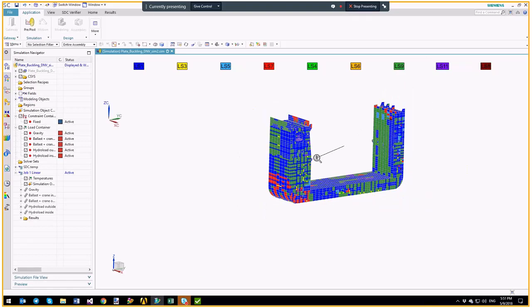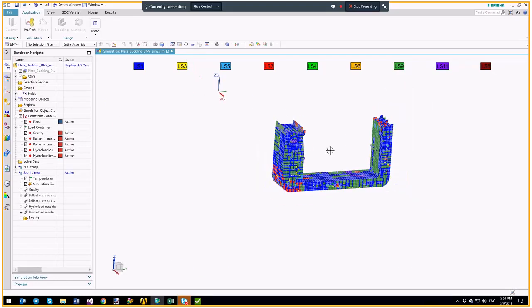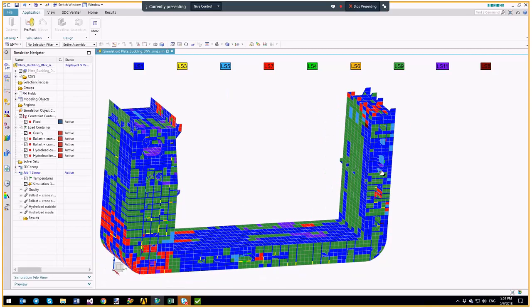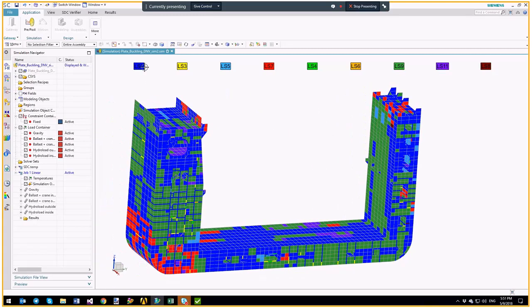So you see with the color. Each load set has a color, and with labels you can see that. For example, green color corresponds to load set 9. Those elements have the highest stresses, and load set 9 is the governing load for them.